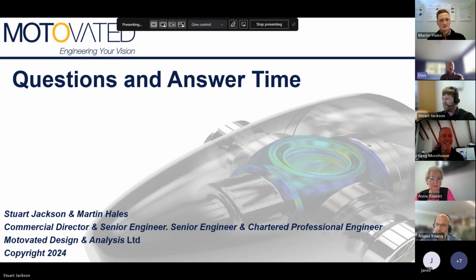For some industries, there are actually WorkSafe design verifiers. So do you have to send some of your stuff through to them, like pressure vessels, that sort of thing? Yeah, correct. For specific equipment like pressure vessels of a certain pressure rating, or cranes where they are powered in more than one direction, we would normally still do our own design statement for certain aspects of that, but it would then be checked and reviewed by a design verifier, and they would do their part.